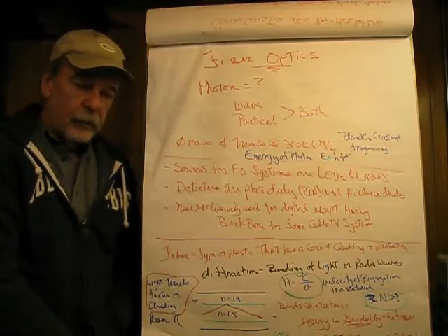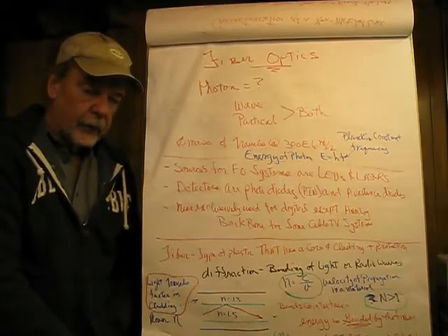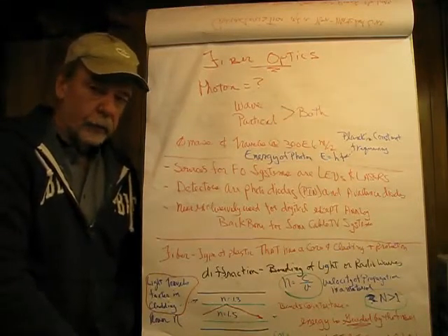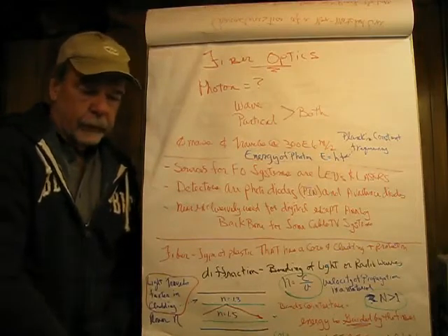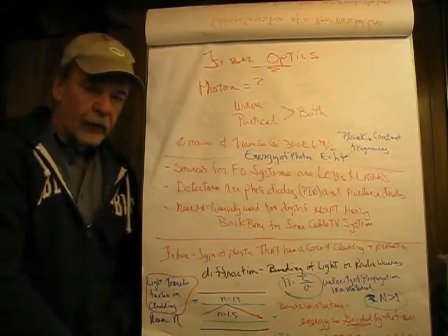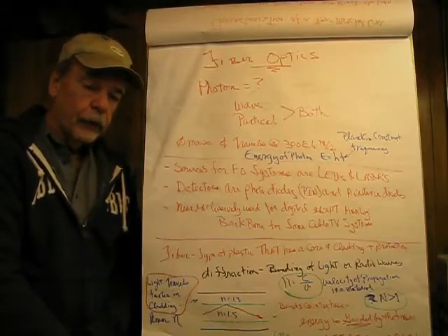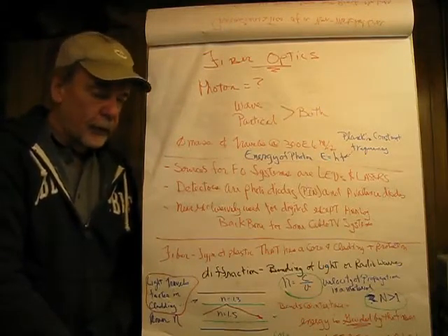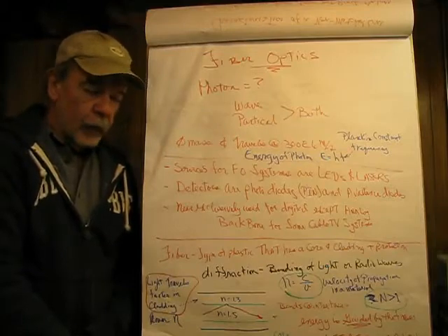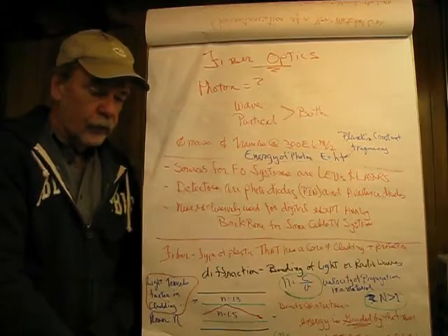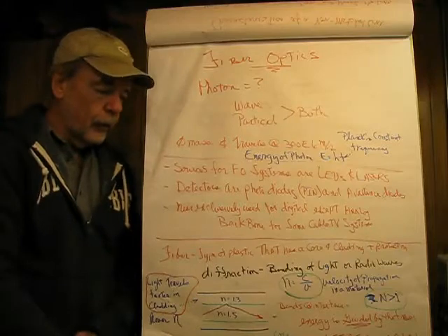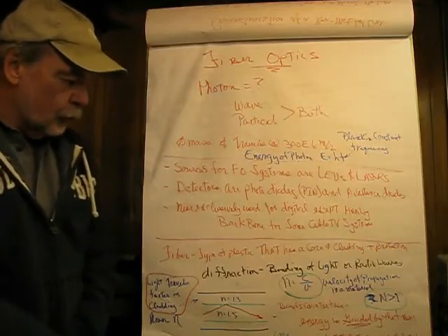Now you can kind of see by the range of that an APD is noisier. You don't know how many electrons it's going to generate. It's more sensitive, and the circuitry is more expensive because you have to operate near the breakdown region, certainly not in the breakdown region. So those are the two types of detectors.